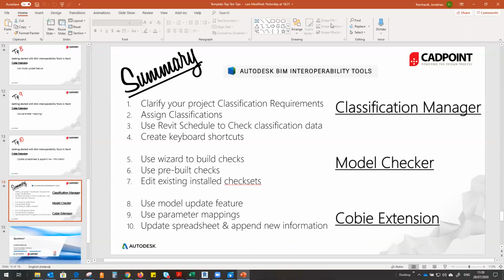There are actually Dynamo scripts that you're able to map to certain parameters just by renaming them. That could be one potential workflow. It depends on the category, but in a lot of cases, if you're just looking at classification, yes, you can select all and update them at the same time, if it's all one classification. Exactly. And if it's a type parameter, obviously it reflects in every instance as well. That's true. Thanks for that.